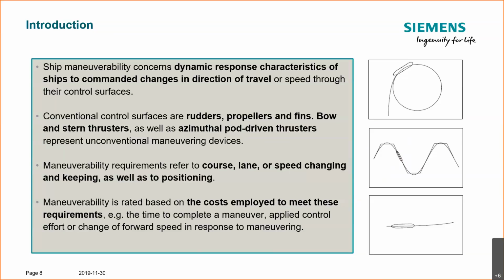We usually rate maneuverability by the cost employed to meet certain requirements. For example, the time to complete a maneuver, course, lane, or speed changing and keeping, as well as positioning, and the applied control effort or change of forward speed in response to this maneuver.